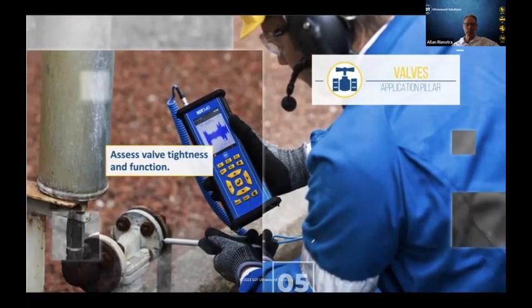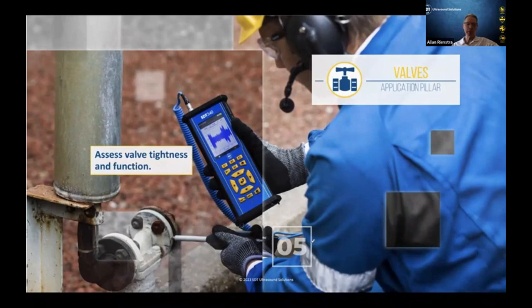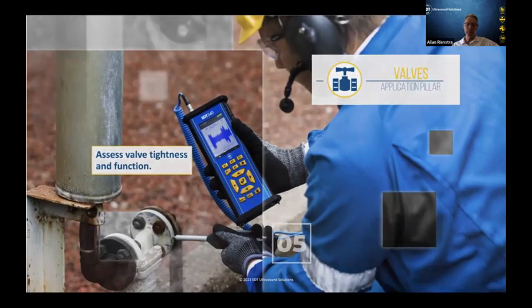The fourth application pillar where we use ultrasound is to assess the internal tightness of a valve. If I've got something flowing across this valve, it's going to produce T for turbulence. If it's producing turbulence, I can detect it with my detector. So if that valve is supposed to be closed and I hear turbulence across the head of the valve, I know I've got a problem.